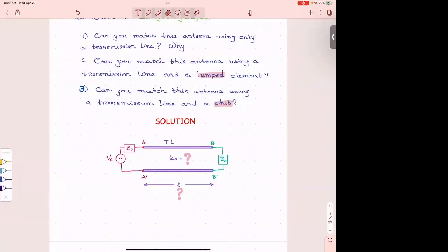So you will have to draw it, that's number one. And then what you would have to do is put down the important parameters. Always, when you have a transmission line, indicate the input port and output port. A lot of times you will see me placing some dotted lines because A and A prime physically are collocated, all right? They are almost next to each other. B and B prime physically are collocated. Why I'm saying that, you will see in the solution.